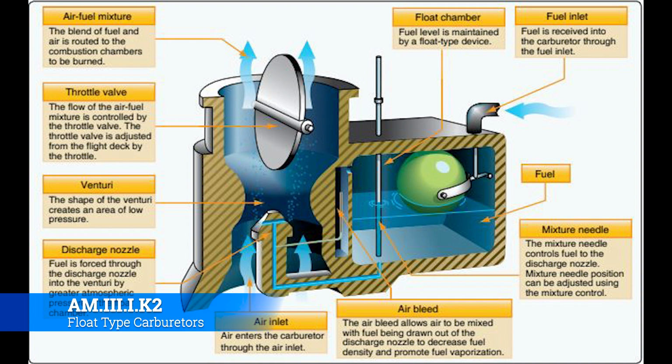Where it will get people in trouble or become kind of a hassle is whenever you have to make adjustments to things like the mixture needle or the idle. There are procedures for that, but there's also at least some subjectivity to adjusting the idle and the mixture to make sure the engine's running correctly, and you'll learn that simply by making a lot of carb adjustments. You'll reset it to the factory settings, and then you'll have to adjust it here or there to get it just right per whatever the engineering calls for.